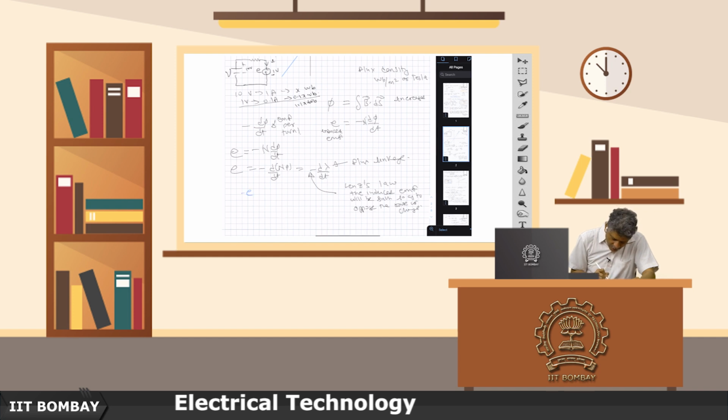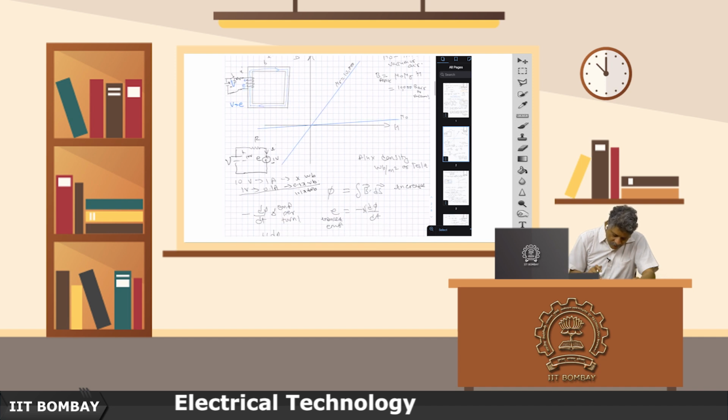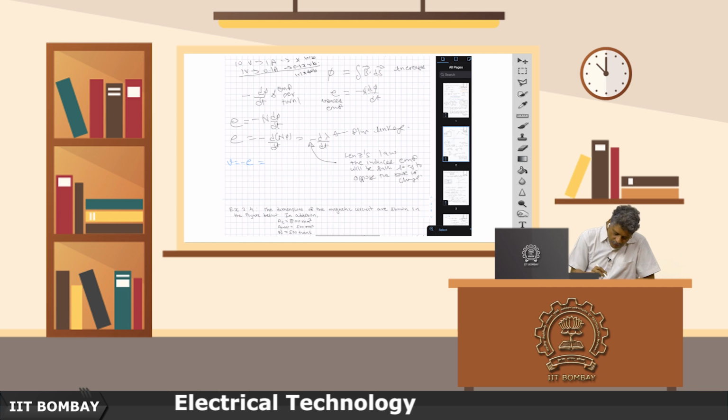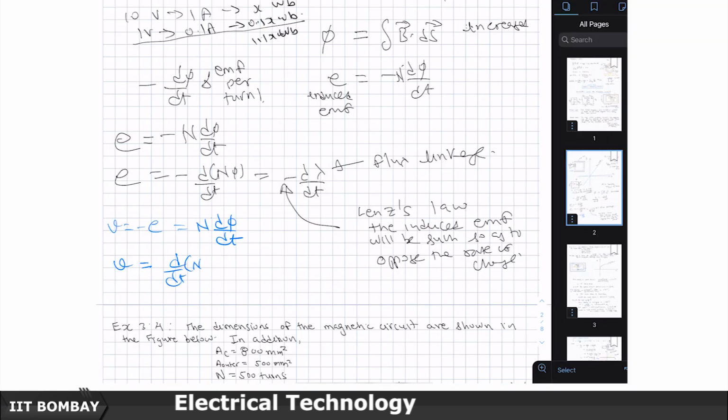Because my polarity marking is already minus of E, and minus of E has been shown here by changing the directions of the plus and minus related to E, this becomes n d phi by dt, which can also be written as V times, I can take the n inside, d by dt of n times phi, or V equal to d psi by dt.